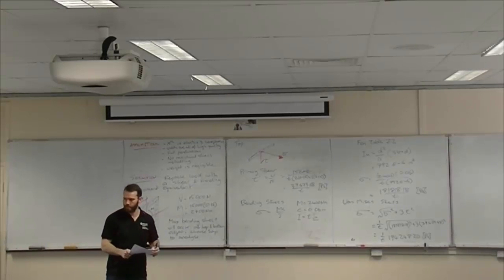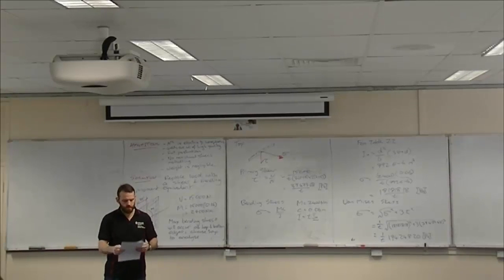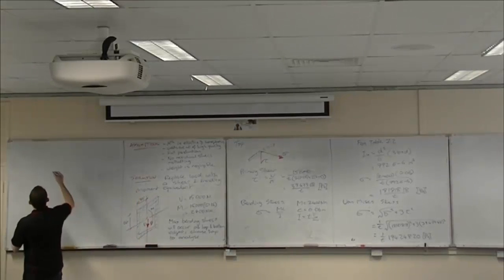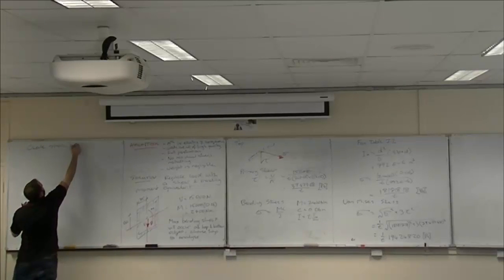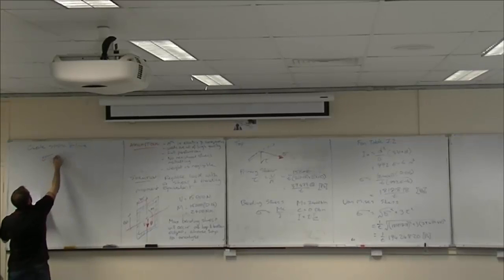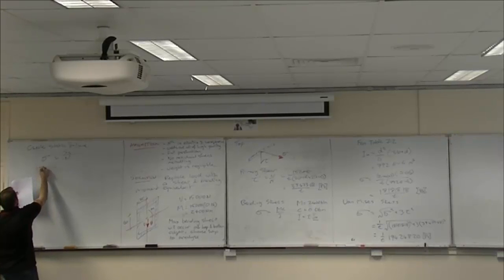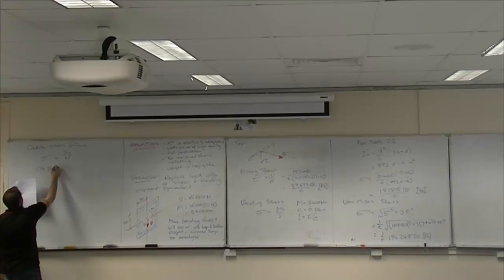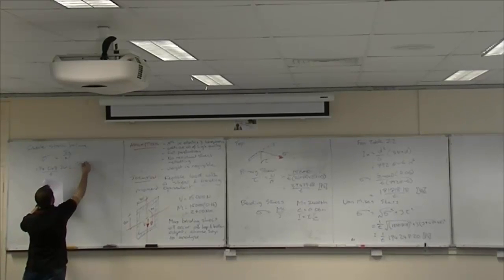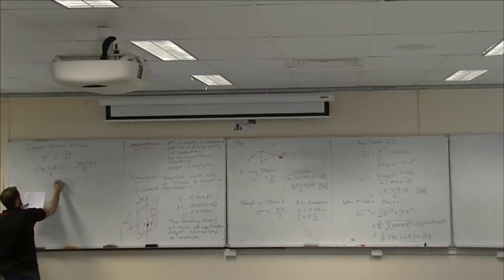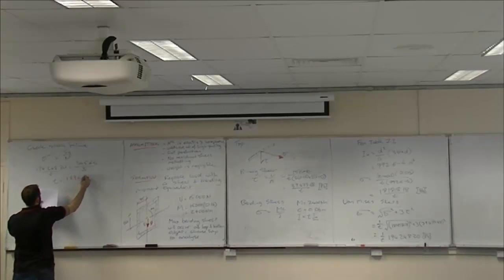Alright, we good? Alright, so next thing, simple equation, static failure, which is just sigma equals Sy on n. So 248.20 on t equals yield stress, which is 345 E6, and factor of safety was 3. Therefore, t equals 1.69 e to the minus 3 meters equals 1.69 millimeters.